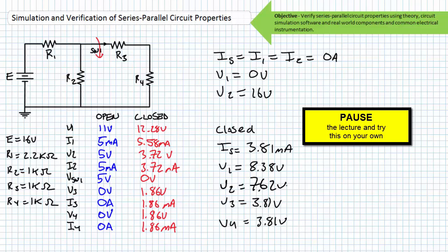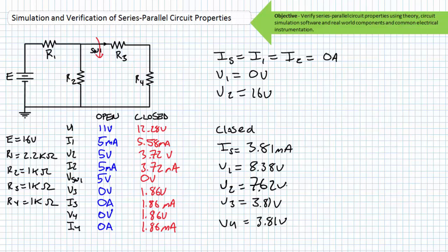Key to the resolution of this troubleshooting scenario is again your understanding of basic electrical theory. When switch 1 was open, current through a pure series circuit ceased. No voltage drop will be observed across elements carrying no current. However, given every voltage rise is accompanied by an equal and opposite voltage drop, all voltage will be dropped across an open.